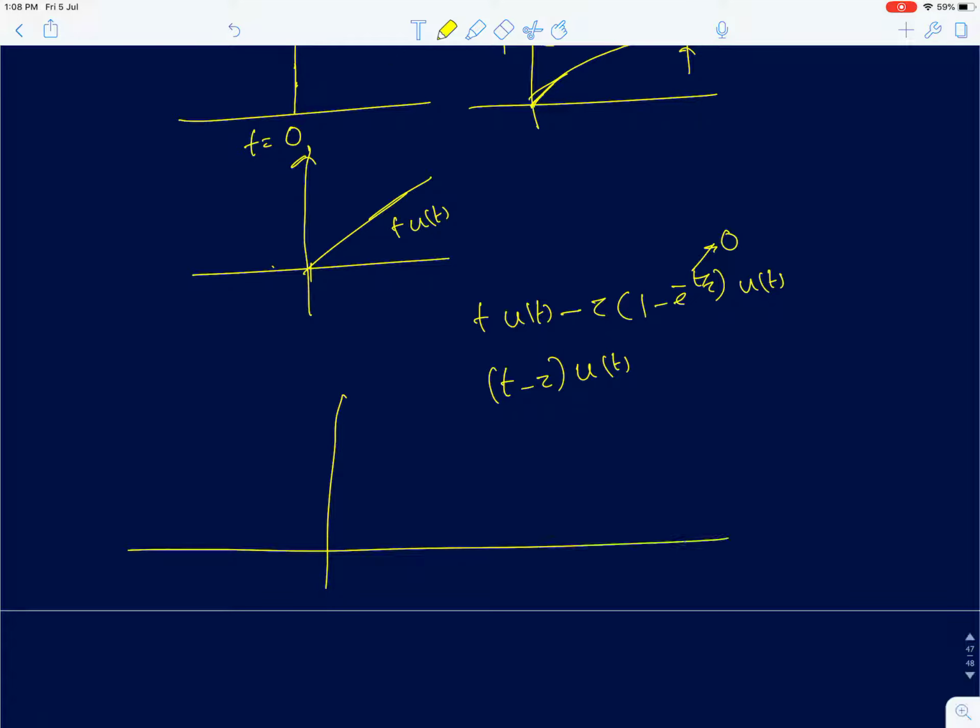So first I'll plot a ramp function and a delayed ramp function. A delayed ramp function starts at t equal to tau, it is 0 here, and it will go like this. Now this is your steady state value. We also discussed that a first order system tries to asymptotically reach the steady state value. So it will start from 0. First order systems, only for impulse it doesn't start from 0. For any other finite input, it starts from 0, and then eventually it asymptotically reaches this value.